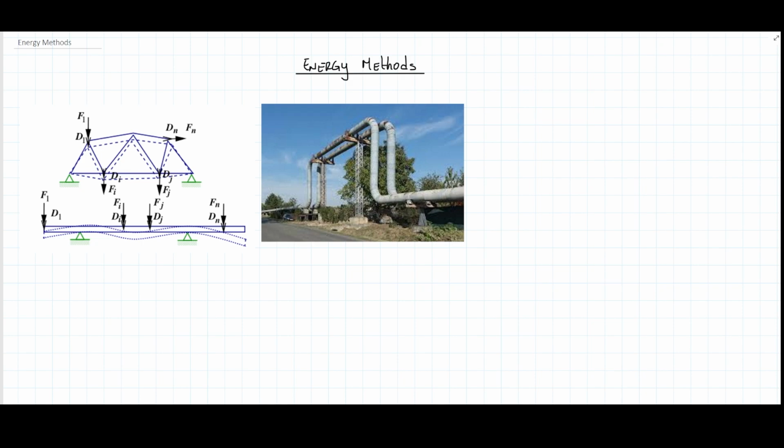And then on the right, you have these typical structures found when there is piping running through or over the ground. They typically make these kinds of shapes because they need to be ready to absorb certain expansion and contraction due to the temperature of the pipe, basically because of the sun or night. That temperature changes the length of certain parts of the pipe, so they have to make these sort of buffers so the pipe won't break. Basically, that's the case for that.